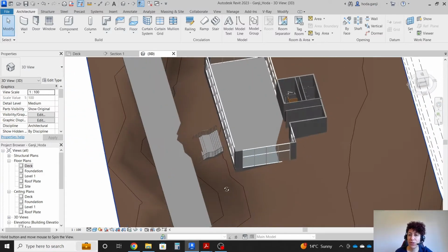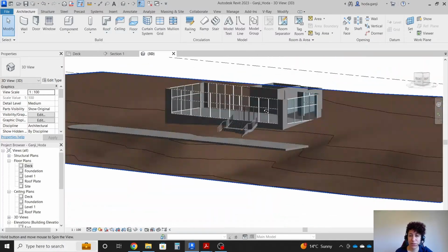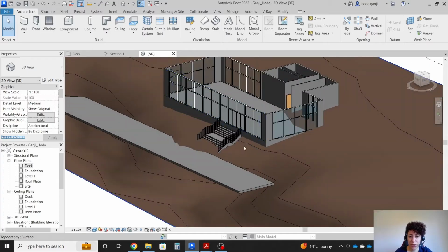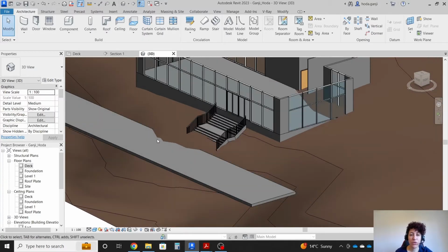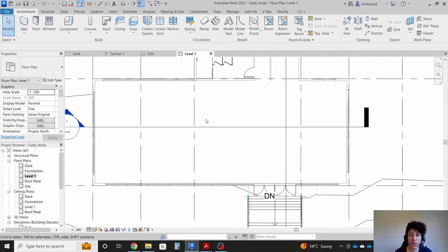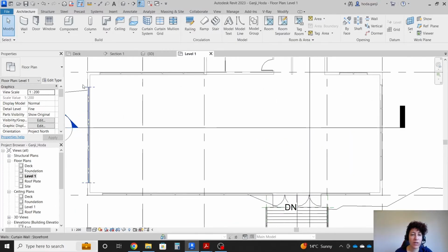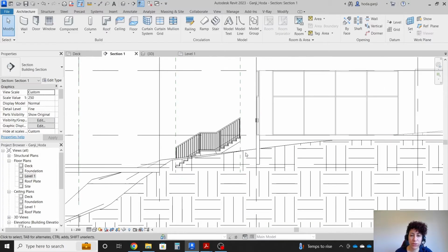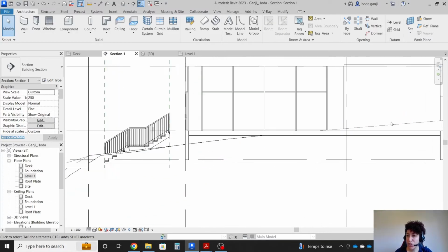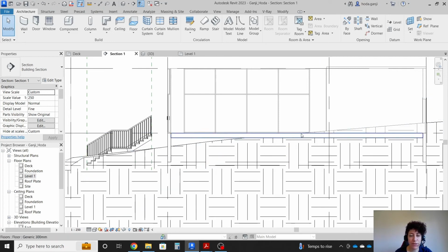So now it's a good time to add some building pads. It's gonna cut some of our topography here, so we wouldn't have any conflict with the soil. So how about first I go to my level 1. I'm gonna need a building pad here, and if I show you in this section, I want it to be inside to inside of the foundation wall.